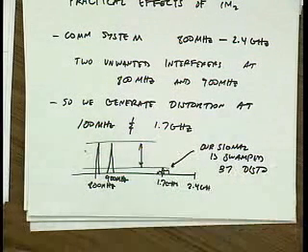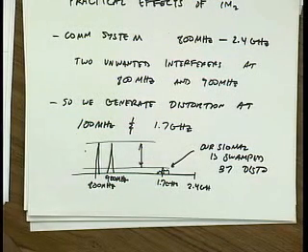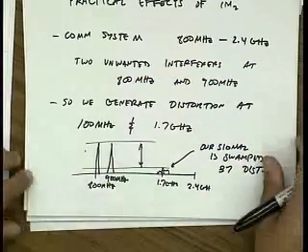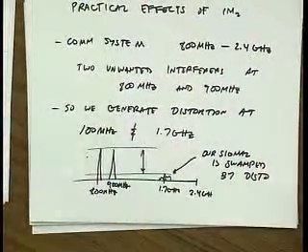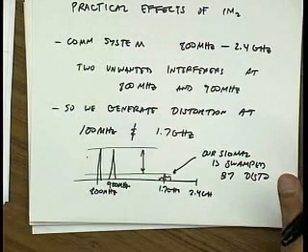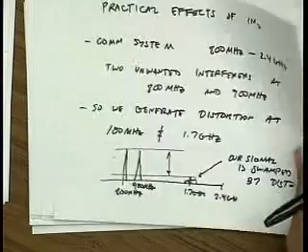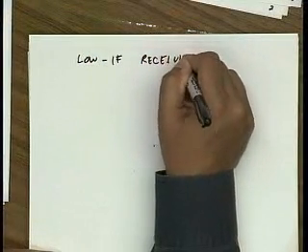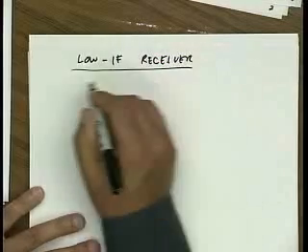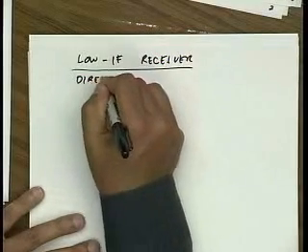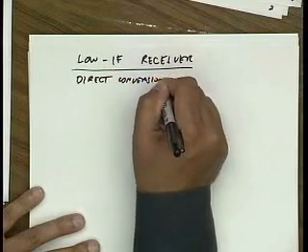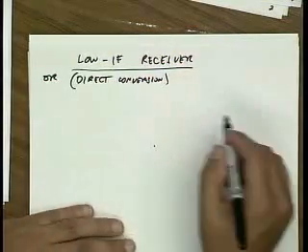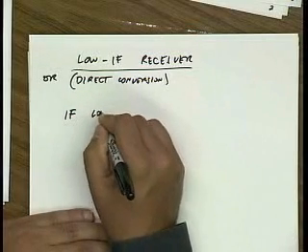So in a wideband system, in answer to the earlier question, certainly we need to worry about second harmonic, third harmonic, and intermodulation. What about a narrowband system? One solution would be, okay, if you have a narrowband system, then both the difference frequency and the sum frequency are always going to be out of band. But it turns out that there are certain situations, like a low IF receiver, where we're using either low IF or direct conversion, where the IF frequency or the intermediate frequency is low frequency.